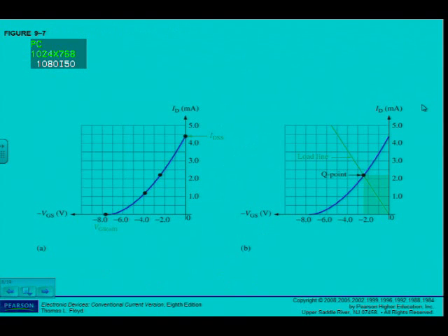Remember, you know how to do this. And remember, self-biasing, I know how to. I have to determine when ID is equal to 0, then of course VGS is also equal to 0, and the other one was where ID is equal to IDSS. Then I had to determine that value so I can plot the second point, connect the two lines and get the load line. Remember to make sure that you know if you're working with a self-bias or a voltage divider biased circuit.